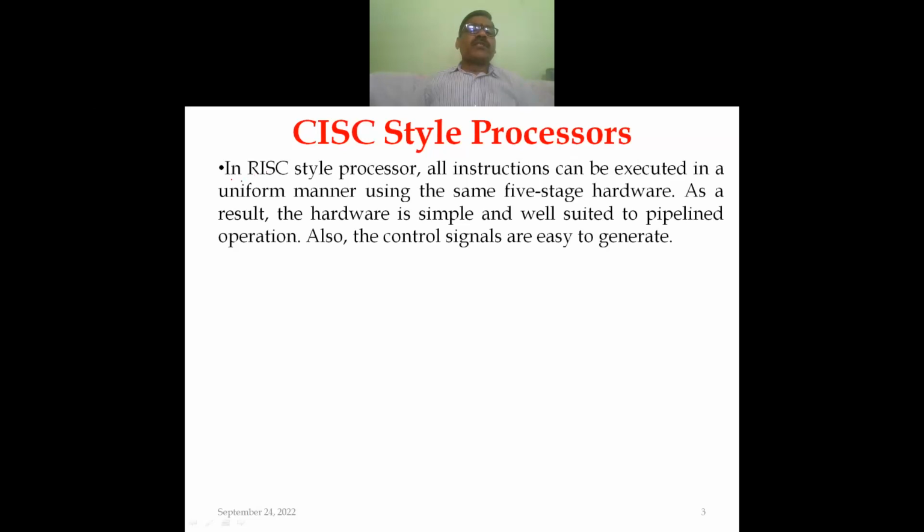We are already familiar with RISC style processors, where all instructions can be executed in a uniform manner, whether it is a load instruction, store instruction, or any arithmetic logic instruction. It always follows the 5-stage hardware for execution.